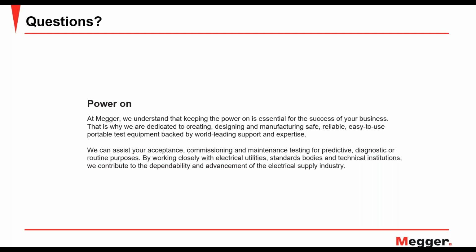All right, excellent. Sanket, the question for you is, can the Frax perform DFR functions if the windings are shorted and not grounded, as in the standard power factor / winding capacitance tests? Okay, so I have had a question similar to this before from other people. People do tend to get confused a little bit between SFRA and DFR, because both tests are done at multiple frequencies.